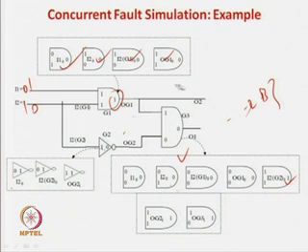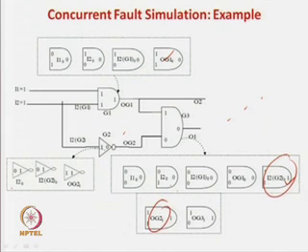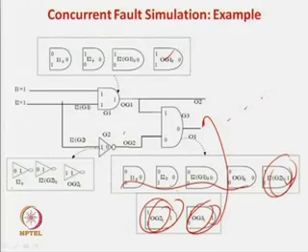But in case of this deductive fault simulation, even with the fact that we have only the set of say 1, 2, only these 3 pieces of information will be available because they are being detected. So, these unnecessary things are not there, but whenever there is a change in pattern, you have to redo everything. So, that is a big trade off. So, if you are doing a deductive fault simulation, then at the output you will have information about only these 3 faults, because these 3 faults are detectable by this one. The information about these unnecessary 4 gates will not be there, because their output is 0 and in the normal case it is 0. So, the faults are non detectable, they will not be there.